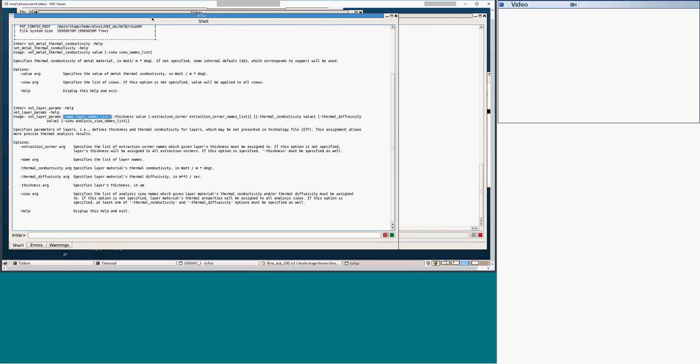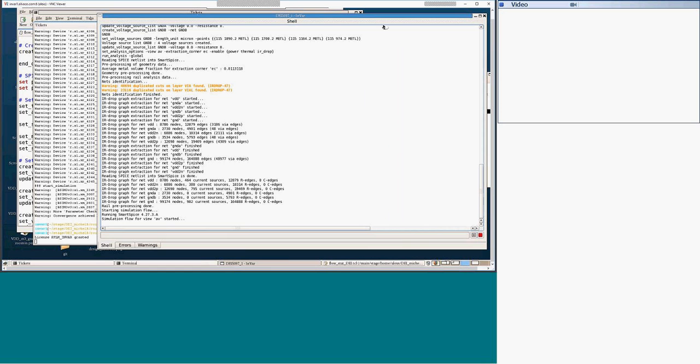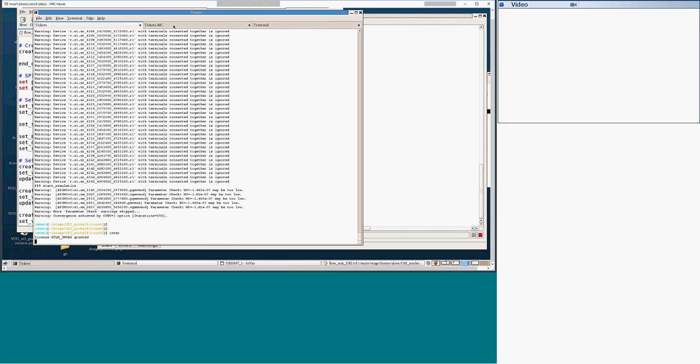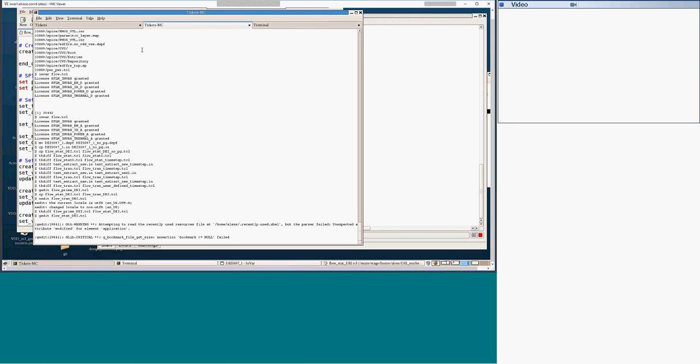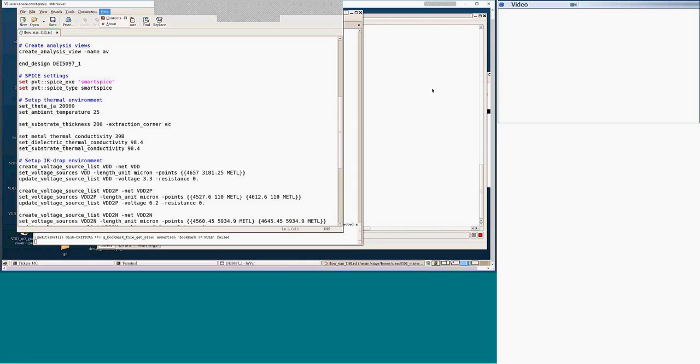I have a question on the Spice netlist. I think yesterday you showed us the Spice netlist. The model file shall use the vtl.inc file. Can we just use the regular library file that XFAB provided?